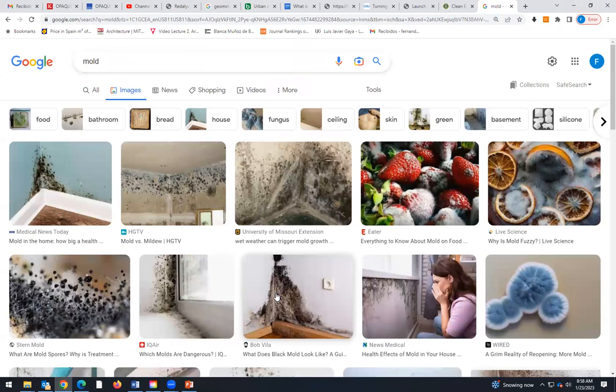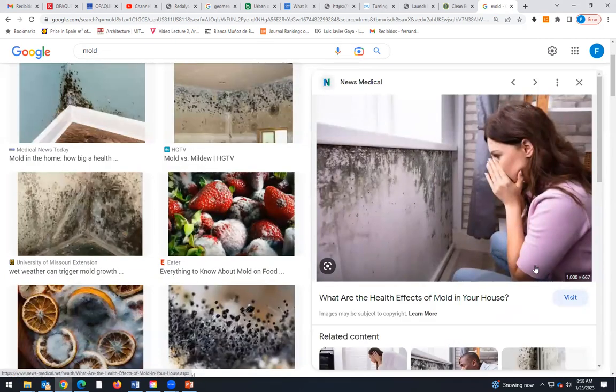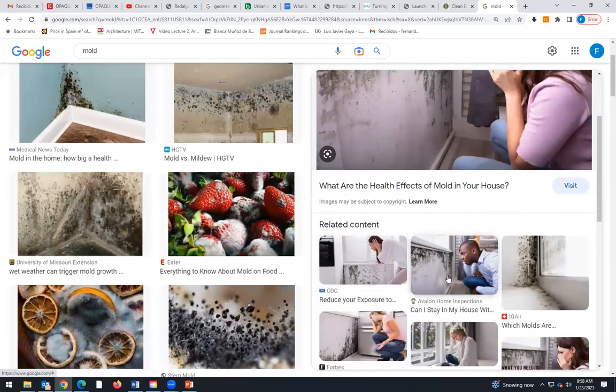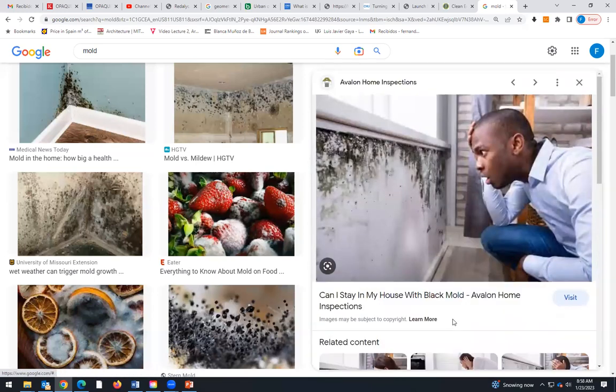This is it. When we have moisture and the temperature is cold enough, we have these kinds of things inside our house. First, it's disgusting. We don't like to see that. And second, some of these molds can be dangerous for health. So be careful with that. And that happens usually when we have thermal breaches. And when it happens, it means that inside is even worse.